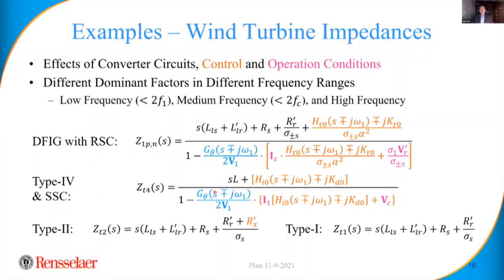However, this transfer function of the phase lock loop is only active in a narrow frequency range near the fundamental. That's the bandwidth of the phase lock loop. If you keep a reasonable bandwidth in the phase lock loop, these functions would only have appreciable gain near the fundamental frequency. If you move 10, 20 hertz away from the fundamental, then this gain virtually disappears.